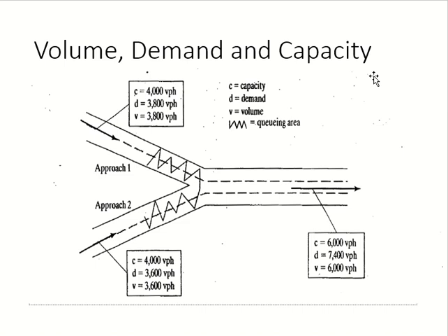So here the demand was equal to volume because volume was less than capacity. Same thing here. To get the demand of this segment, we added these two. So the demand was more than capacity, so volume equals capacity. Clear? Okay.